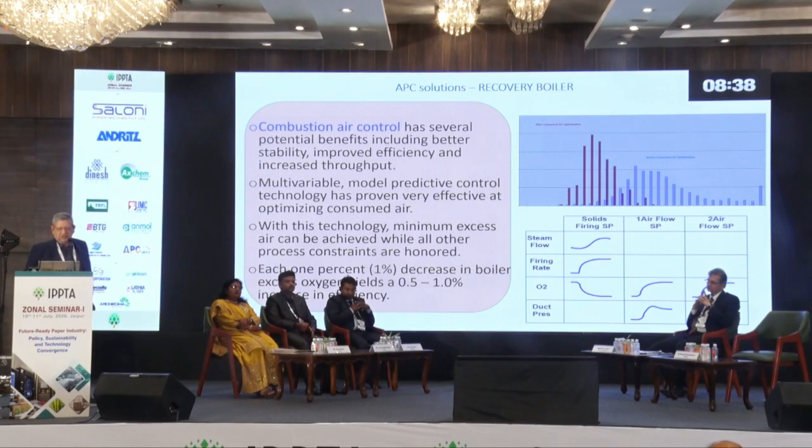There are a lot of slides relating to that. You can see here, every 1% decrease in boiler excess oxygen yields a 0.5 to 1% increase in efficiency. These people have to think deep to understand and then try to implement this.